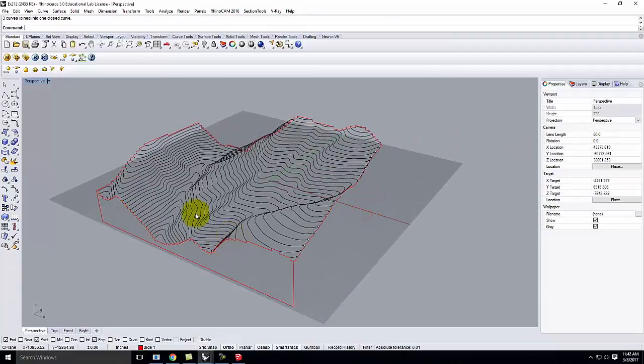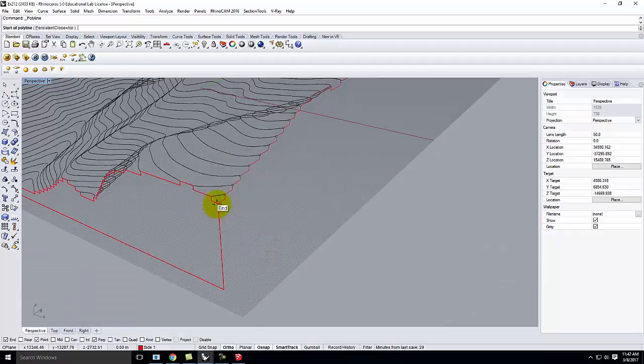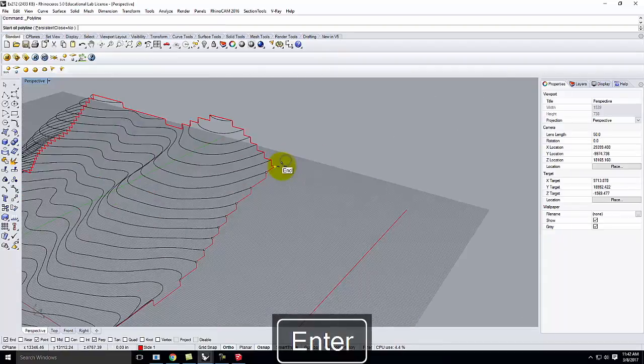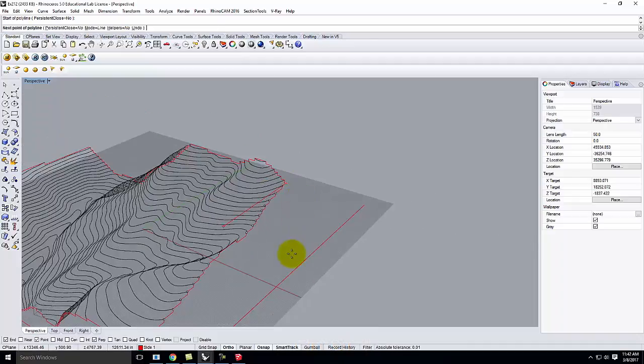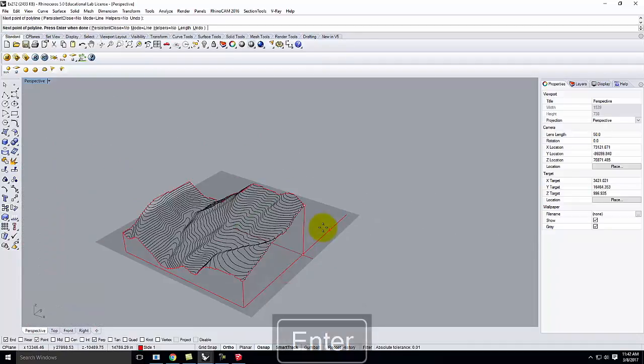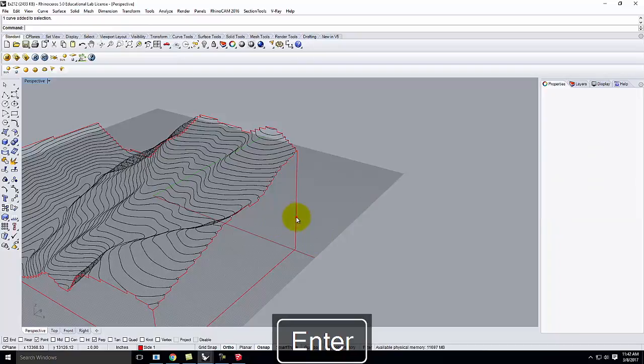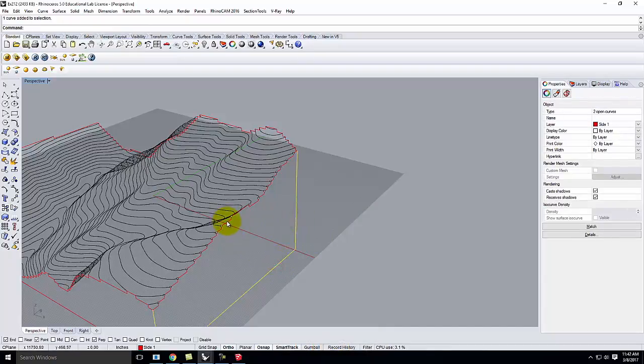So once I have the one side done, we can continue with the other sides. We're going to have duplicate corners, or duplicate edges on the corners. I'm just going to copy to there and there. We'll go off in this direction. We'll go from this corner straight down, snapping to perpendicular right there. We'll go ahead and trim. Enter to finish. This plus this plus this then become the next side.